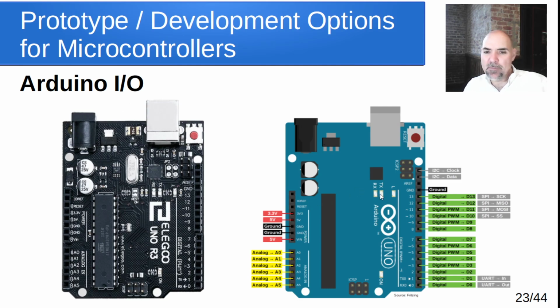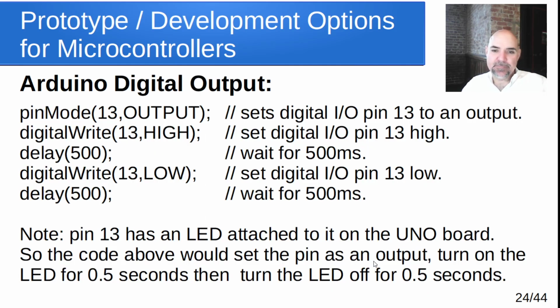And it also has some onboard LEDs here that you can interact with. This LED you can control. It's connected to pin 13. And this RX and TX are used whenever something comes through or goes out of the board through the USB for communication, or it's actually connected to the UART pins. But you'll notice that gives us the ability to see if it's communicating or if it's working. And we can use this LED for whatever we want.